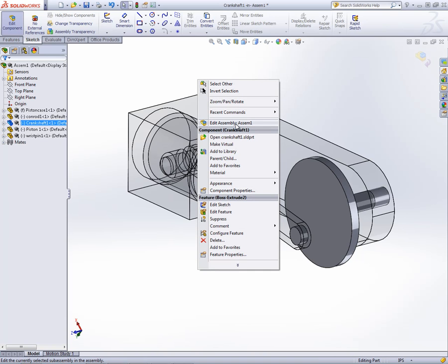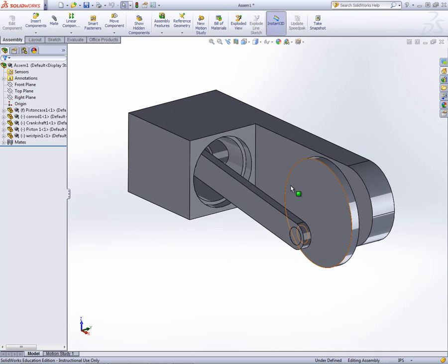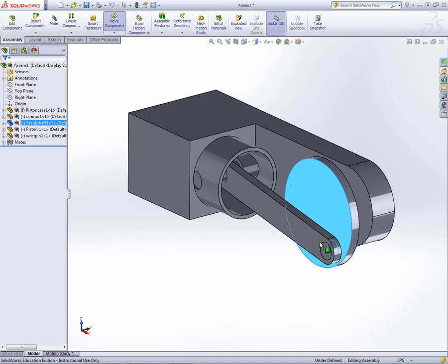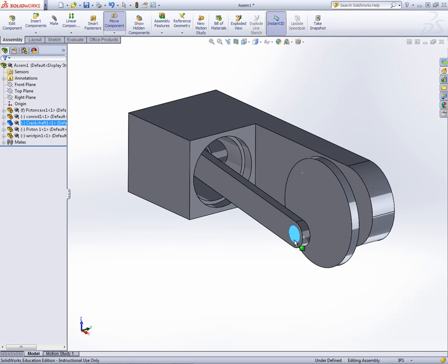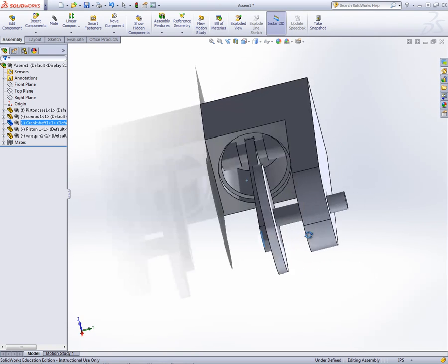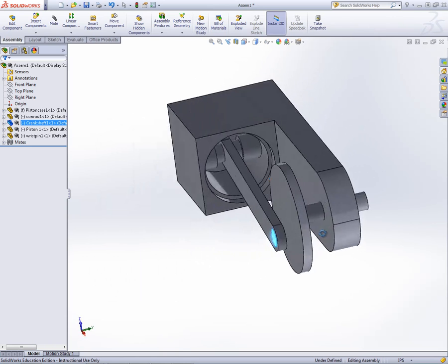and left click on Edit Assembly: Assembly 1. That gets us out of the editing area. And so now the connecting rod doesn't interfere with anything, and if you push the mouse wheel down, the crankshaft pin goes clear through the piston case.